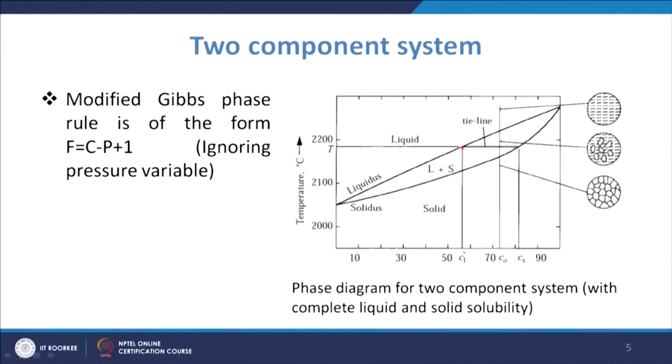So, that is being calculated with the help of the lever rule. Now, the lever rule tells that if you take this point as the fulcrum of the lever, the fraction of this upon the whole will be the part of the solid, and the fraction of this upon the whole will be telling you about the part of the liquid which is there. Basically the line is touching the liquidus line. So this fraction will be the fraction of the solid formed, and this fraction will be equal to the fraction of the liquid.